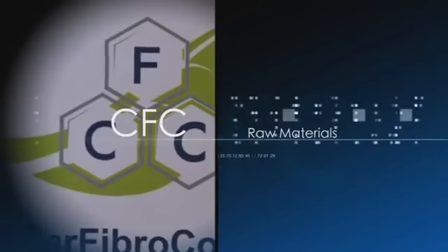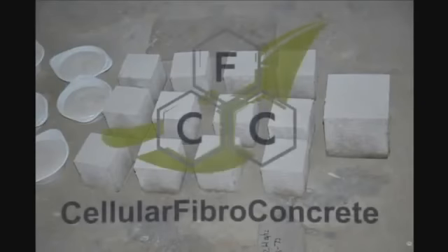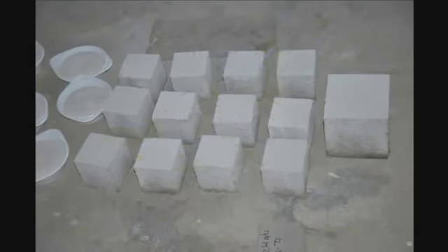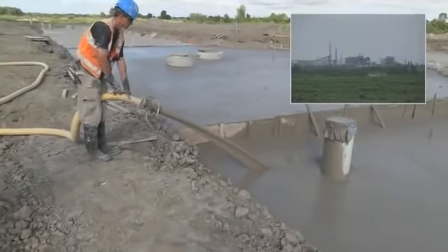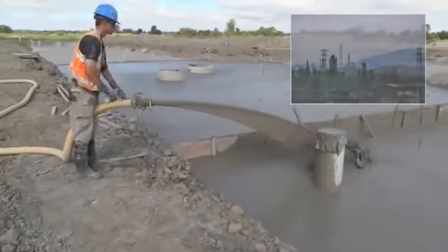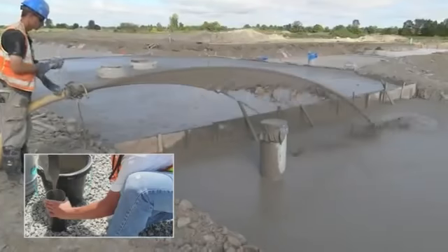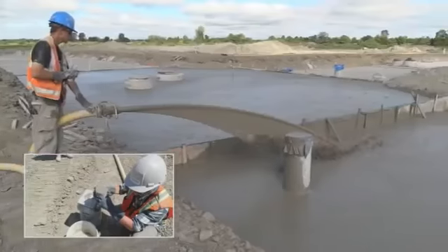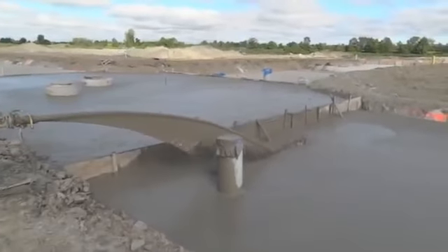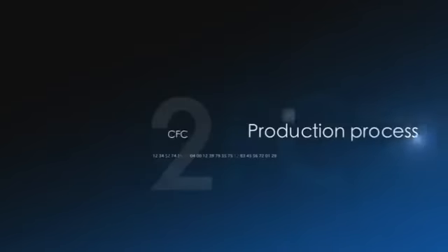Raw materials. The dry mixture, CFC, is produced from mineral raw materials, from sand, and from waste products of the petrochemical and metallurgical industries. The mixture is produced from Portland cement of any type, CEM1 or CEM2. The other main ingredient can be either sand or fly ash or metallurgical slag, which contributes to solving the problem with utilization of these waste products.